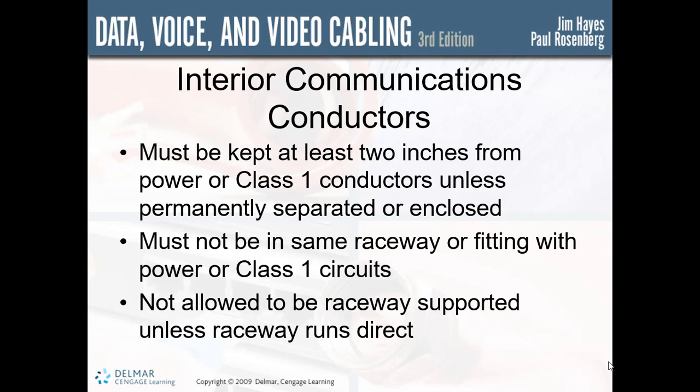The interior communication conductors. Communication conductors must be kept at least 2 inches away from power or Class 1 conductors unless they are permanently separated from them. Class 1 conductors are enclosed in one of the following. You can use raceway. It can be type AC, MC, UF, NM, or NMC cable, or a metal sheathed cable.